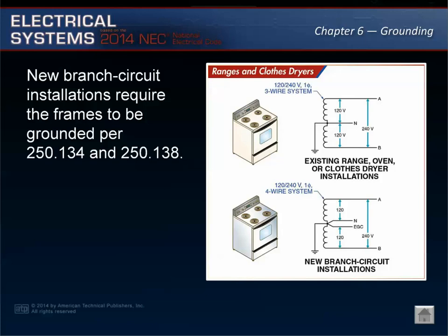The grounded conductor was at least a number 10 copper or number 8 aluminum. The grounded conductor was insulated, or if uninsulated, was part of an SE cable branch circuit originating at the service equipment. The equipment was bonded to the grounding contacts of a receptacle which is part of the equipment. The change no longer permits the use of the grounded conductor for this application. The change does, however, only apply to new branch circuit installations.